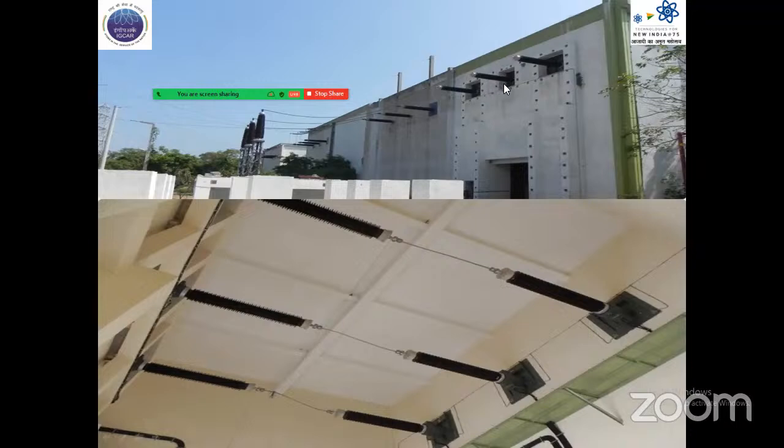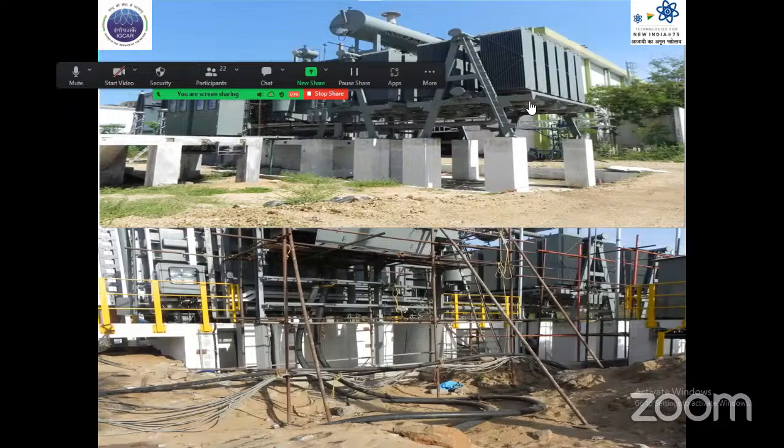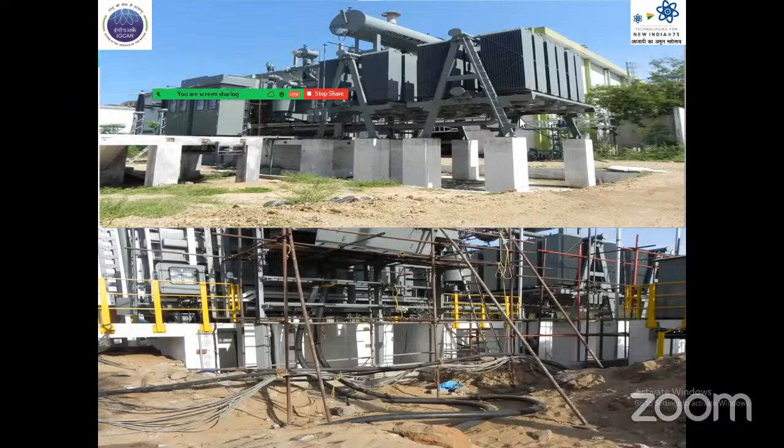installed. Even though the weight of the bushing is around 1.7 ton, we have used a 25-ton crane because of the higher boom length that we required. Because of that, this one challenge we faced and overcame. And this is the drawing which shows the power and control cabling going in this transformer. After the installation of transformer and radiators and cooler control cubicle, the photo shows like this.